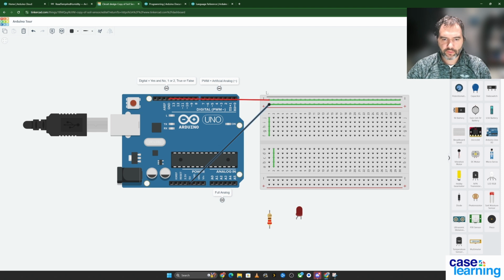So the breadboard itself has a rail here with the negative and the positive signal going through. And down here you notice that the green lines are going vertically. That is where we're going to stick our pin wires. So you can have a pin that goes from port 9 to your signal. Then you would go from 9 over to this point, and from there, anything that's plugged onto this one section will be connected with that in the circuit. So go from the 9 over to the 1.